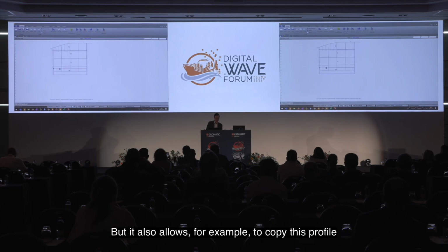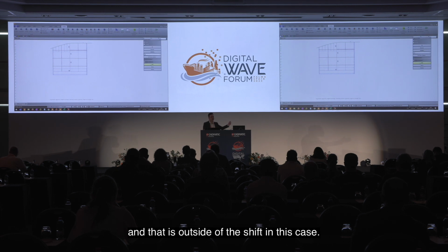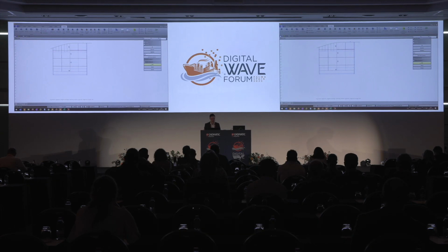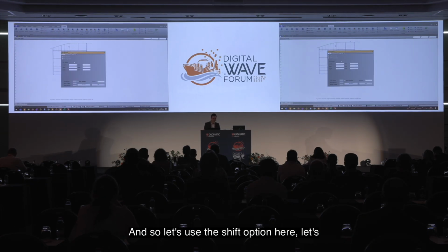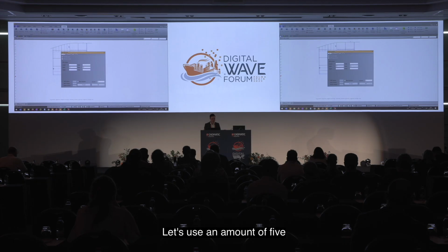But this also allows, for example, to copy this profile nicely to a positive direction, and that is outside of the ship in this case. And so let's use the shift option here. Let's use just steps of B1, because that's the default grid. Let's use an amount of 5.